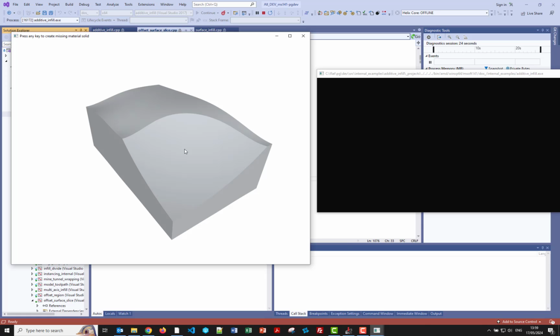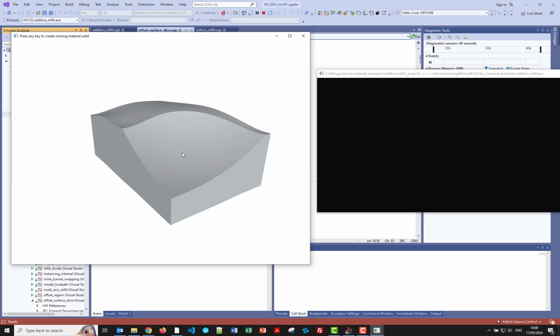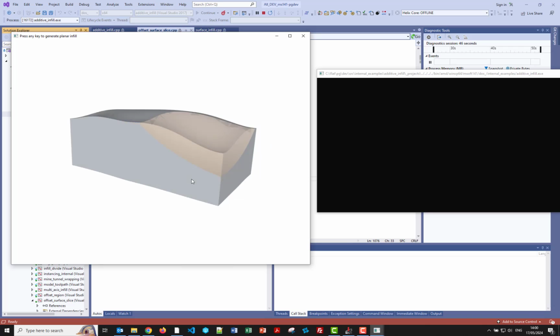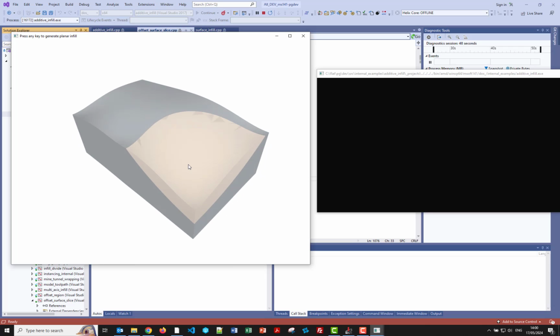First of all, Polygonica's Boolean is really good at giving you regions in which you can machine or regions in which you can add material. So in this case, you would take, for example, the laser scan of the worn part and subtract that from the original part, and that would give you a bounding volume of the area you need, the volume you need to actually add material in, which is this golden part here.